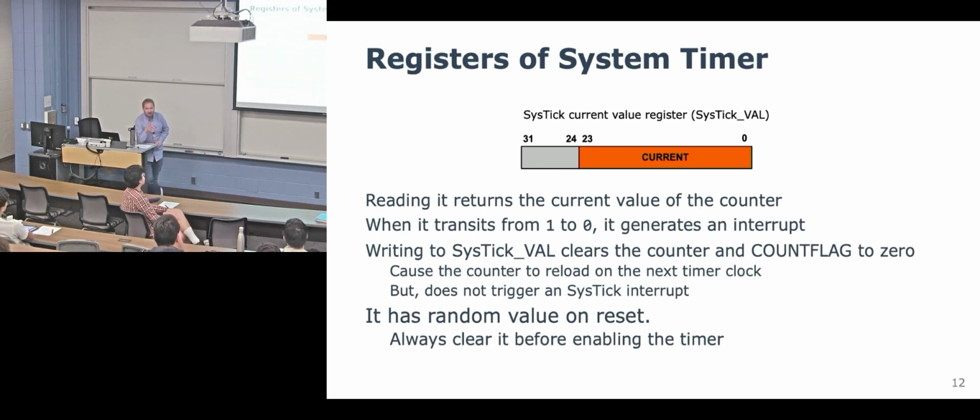Also, when you just boot up silicon, right, you're going from 0 to something, you don't know what value is going to be in your D flip-flops, right? So you'll find that, especially like memory, unallocated memory just has some random value in it on startup. And so it could be some random value in there that you don't know what it is. Now, you might say, oh my gosh, all those cryptography people have been trying to make random numbers for a century.